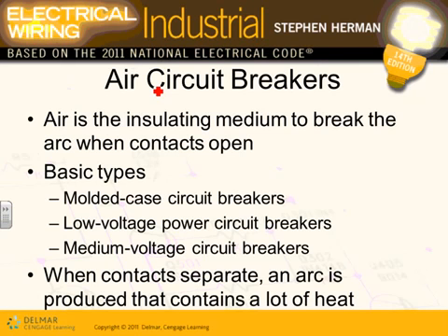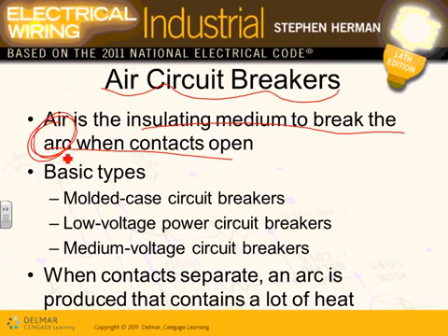Okay, air circuit breakers. Air circuit breaker is the way they design the circuit breaker, guys. The most common one is called air circuit breakers. The insulating medium to break the arc is the air. So these contacts are sitting up in the air. When you open and close them, you open and close them in the air.